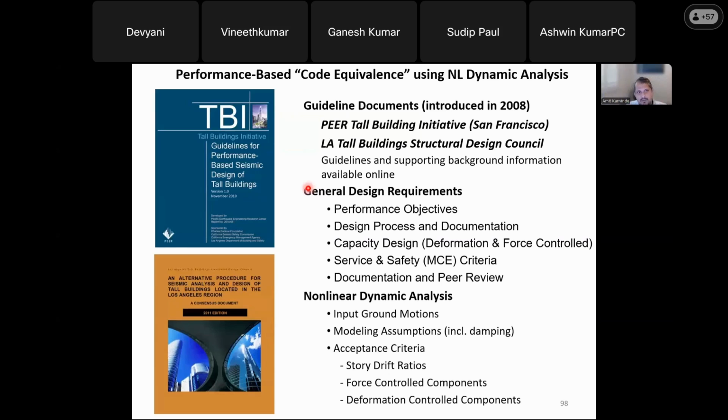Okay, so a lot of this performance-based analysis is currently being used to actually economize your structure, because we find that applying the code for each one of these structures tends to be very expensive. And if we can demonstrate by other means that the structure is equally good in terms of collapse performance, we can essentially ignore the code and design the structure a lot cheaper.